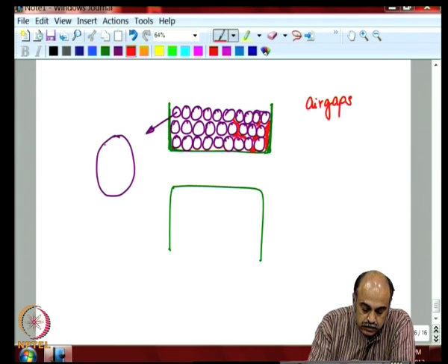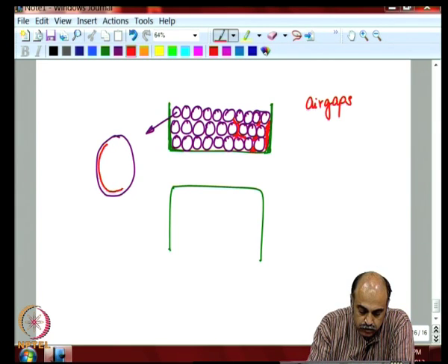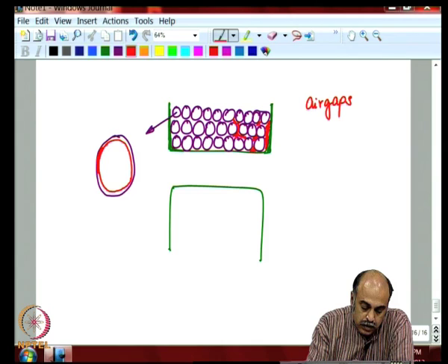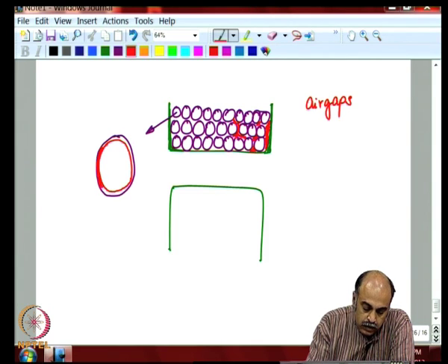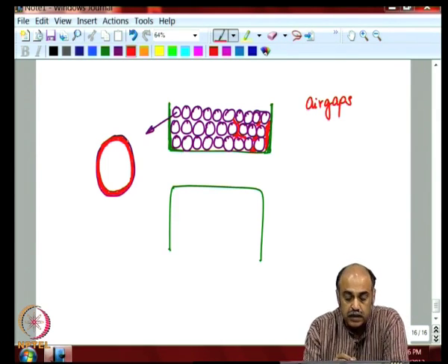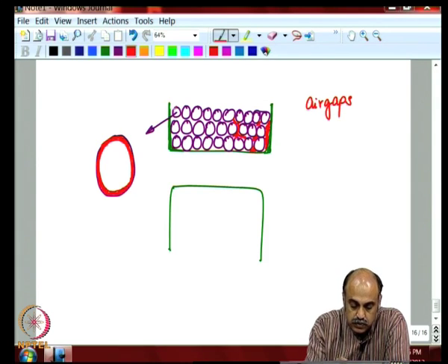One is the outer sheath, which is the enamel, because the windings are sitting next to next. You don't need short circuits happening between the windings, and therefore the wires are covered with a coating of enamel, which provides a natural insulation.